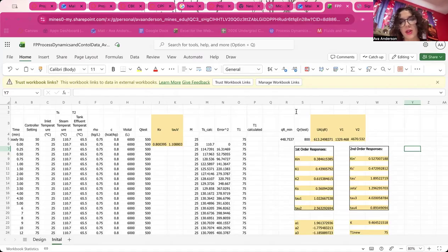KC actual is found to be 6.19, and finally, based on those values, the recommended PI controller settings are KI to be 1.95 and tau I to be 3.18. KC was 6.19. And then we're looking at the closed loop to find a response to a 10 degrees Celsius change in the inlet temperature in Simulink.